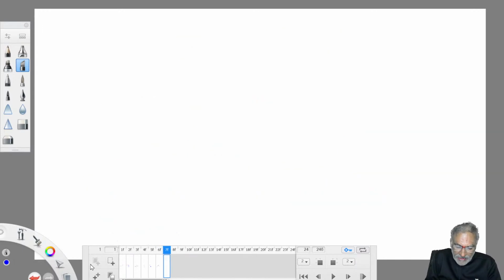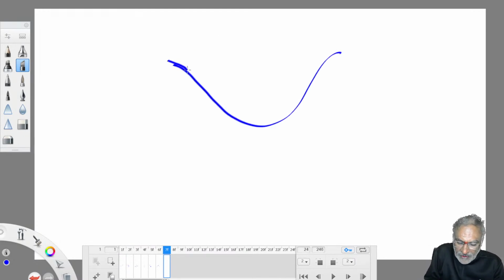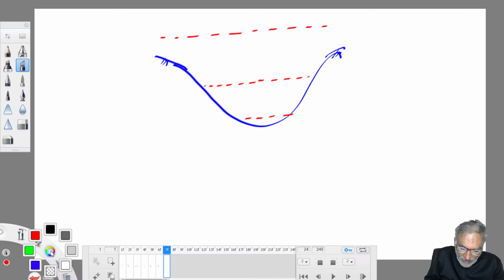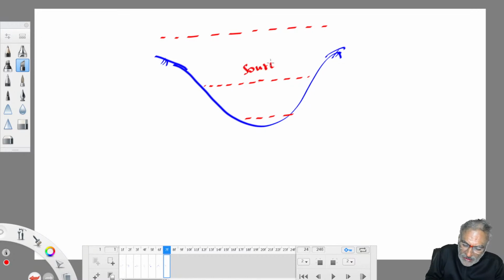What I mean to say is, at surface water bodies, assume a river flowing nearby. Sometimes the water level in the river is at the highest point, sometimes at the lowest level, sometimes somewhere in between, sometimes water flows above the banks also. But irrespective of the water level at the source, we need to collect a constant amount of water. Normally this collection is made with the help of pump and pipe. Those pump and pipes we install to collect water from the source should be protected irrespective of the water level at the source. They should not wash away along with the water.